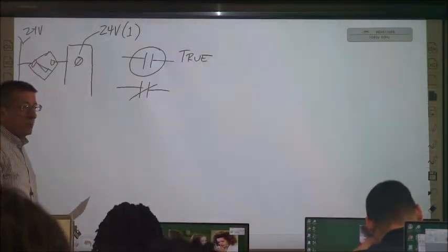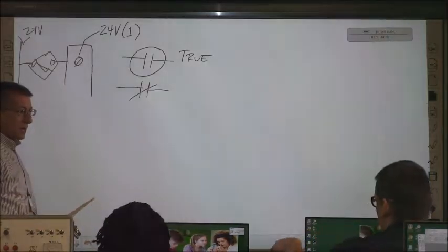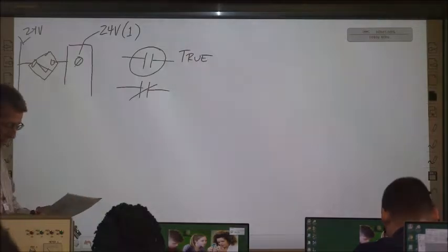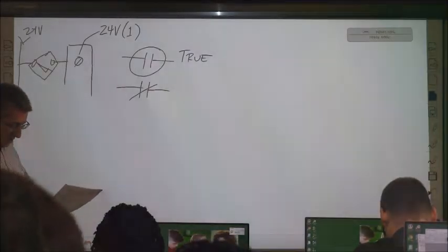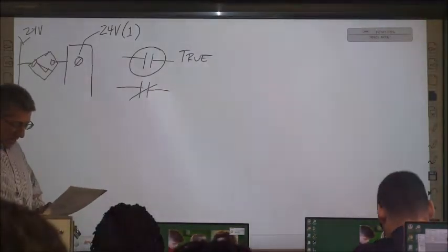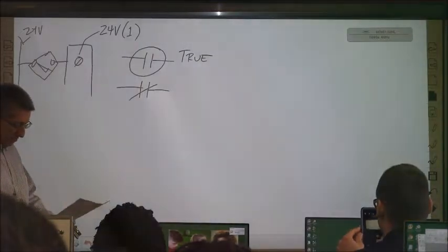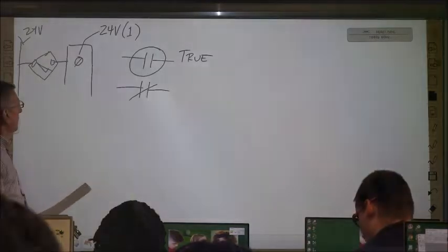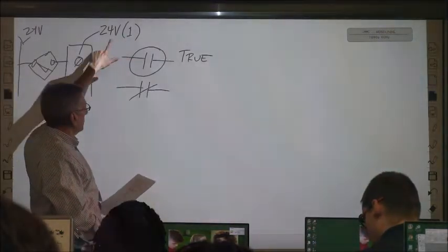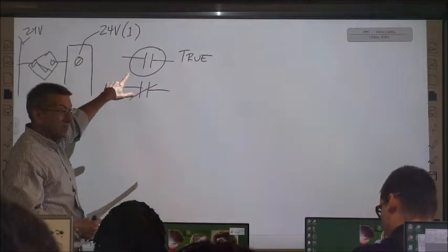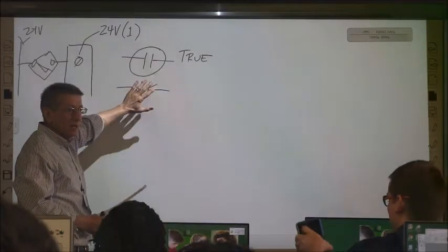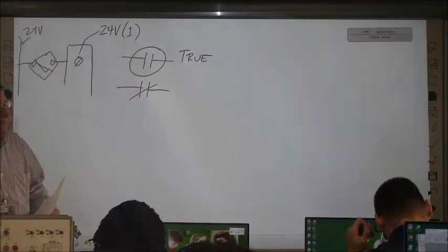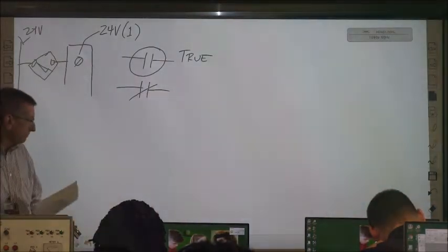Everybody get that? Because we want logic continuity, right? And then what's it say? It says, in XIO, and then the proximity switch is made. What will be the state of the instruction in the logic? Right now we have a 1 in the PLC because the proximity switch is made. And the XIO requires a value of what to be true? 0. Yeah. Good.